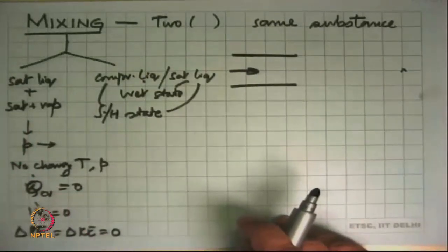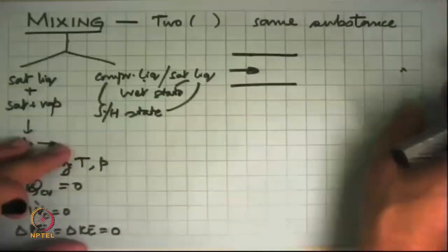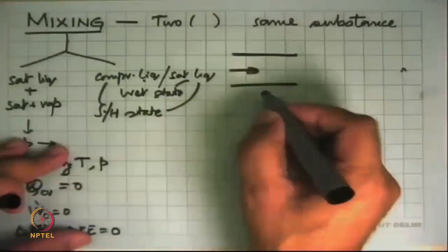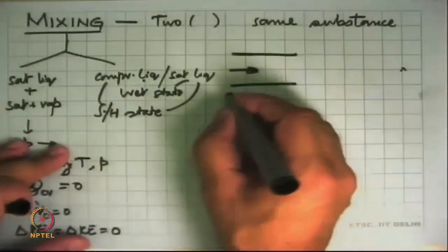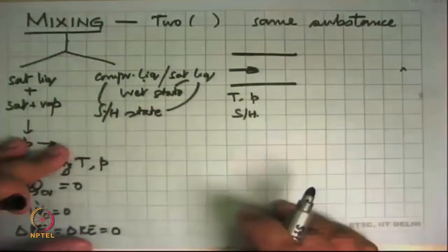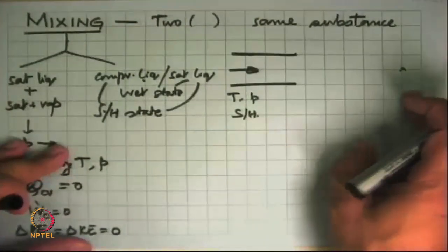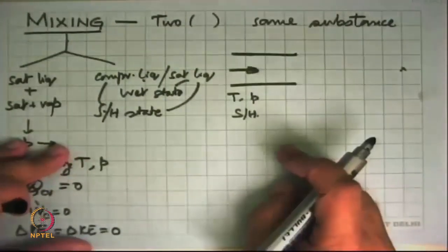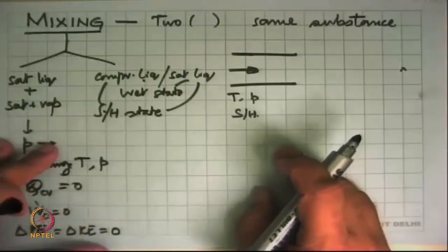So it will throttle it, so you can only reduce the pressure and maintain it constant. You cannot increase it. But what if I want to reduce the temperature of this? Then theory will tell you that if you have steam at a certain temperature and pressure, and if it is superheated or saturated, and you want to reduce the temperature, either you expand it in a turbine or you expand it in a nozzle, both of which are not practical in most cases.